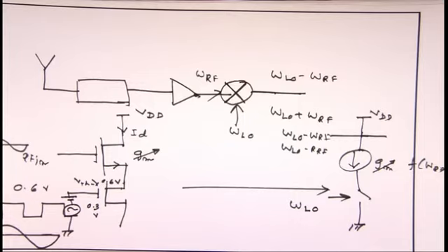In case of an LNA, your input signal and output signal have the same frequency. Whereas in the mixer, the input signal is RF and the output signal is IF. So, we do not call it a simple gain, we use the term conversion gain. That means frequency gets converted and it can also give you some kind of gain. Clear? So, that is the only difference for the analysis, that it is also giving a gain or attenuation depending upon your design, but also it changes the frequency.